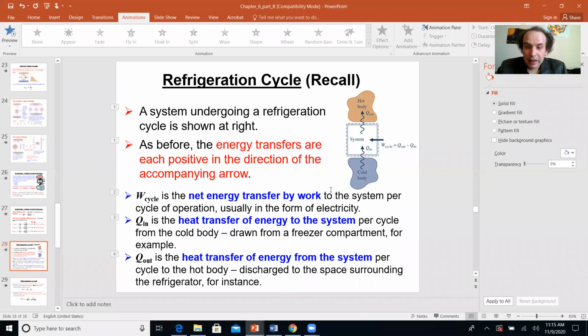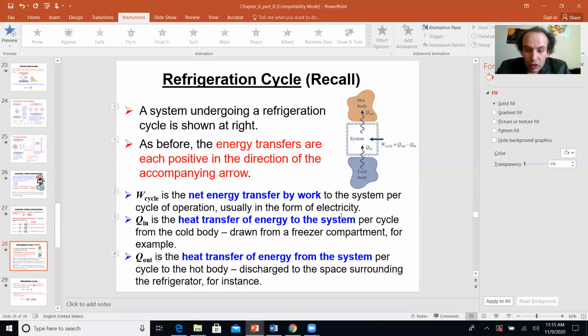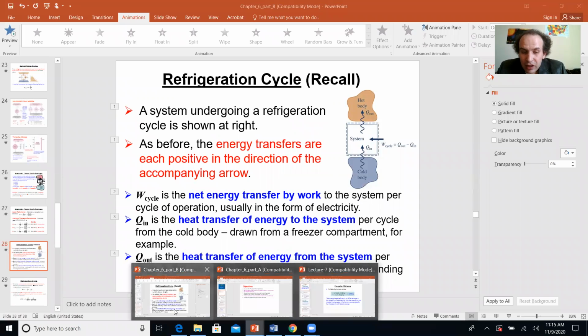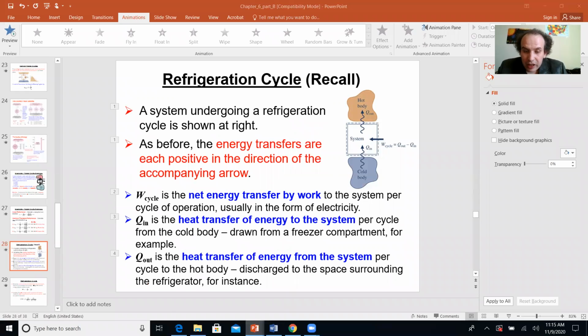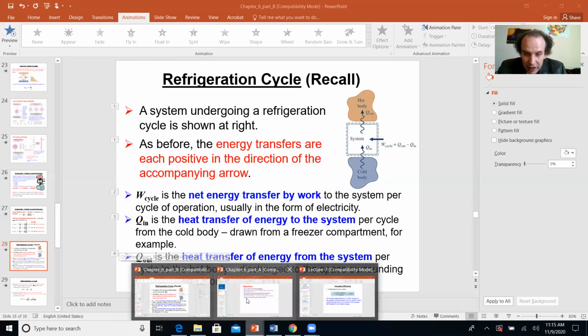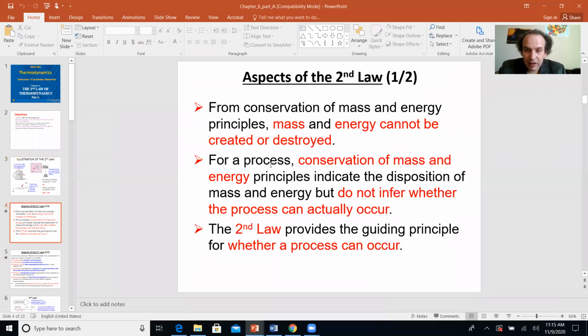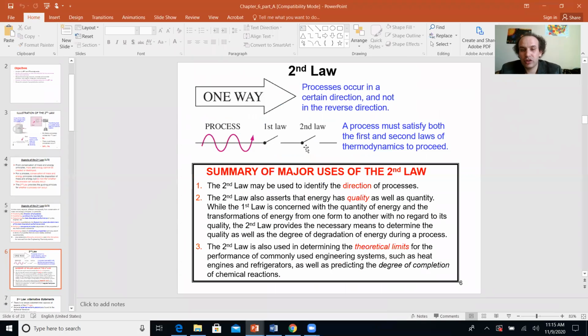Now, what I wanted to say is that when you check the second law, you must check the first law and make sure that energy conservation works. Remember, there's quite a good illustration here with this chain on the screen: you first check the first law and then you check the second law. If the first law is violated, if energy is not conserved, the second law can give you anything. It can give you negative efficiency, larger than 100%. Please don't deal with it.